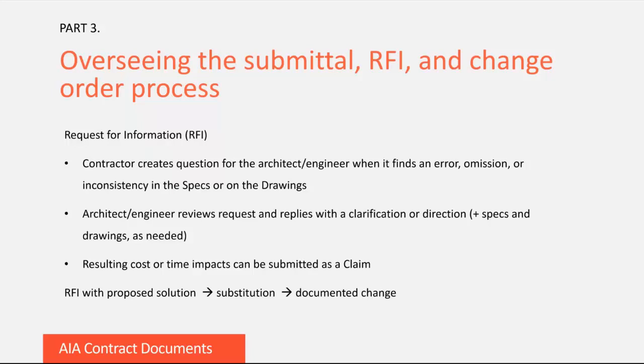Now, should the RFI response create cost or time impacts, the contractor can submit a claim. A simple project may only have a couple dozen RFIs, but a complex project could have thousands. Now, this goes a little bit toward collaboration, but if you identify a problem at the site or a discrepancy on the drawings that leads you to submit an RFI, consider proposing a solution with the question if you're comfortable doing so.